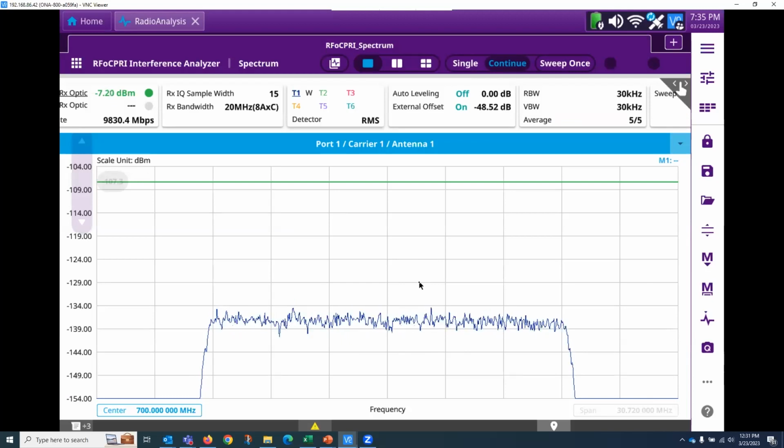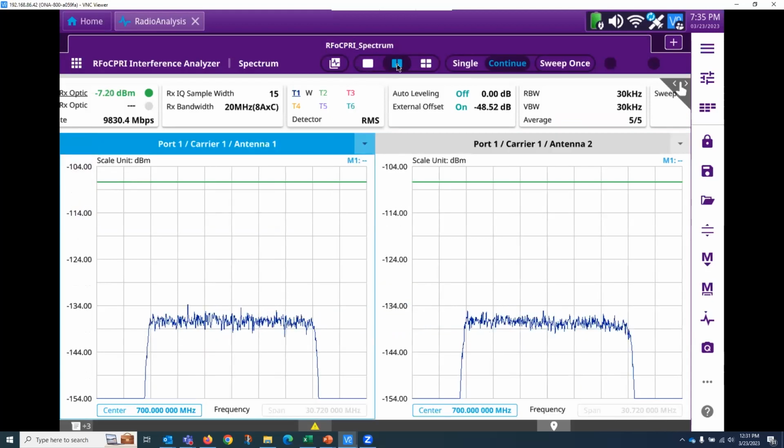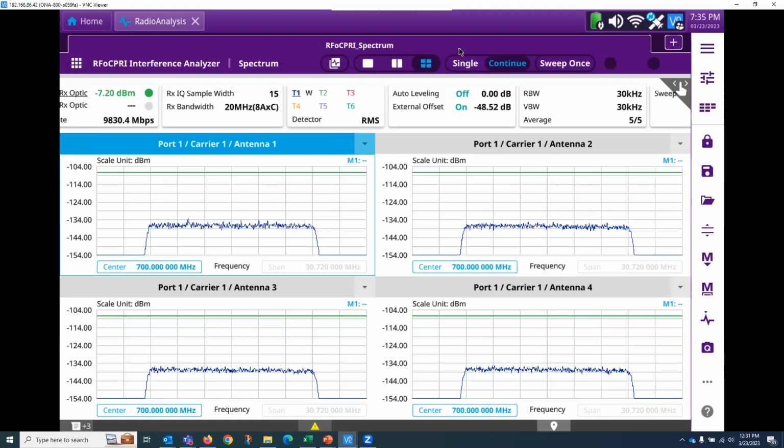Fairly quickly, the system is able to analyze a single antenna. If we're isolating one branch, or if I want to isolate two branches, I can come here and pick my branches, but more importantly, isolate all four branches. So this is our 4x4 MIMO system. You can see we have 4 branches. I do not have any PIM sources in right now, so it looks nice and clean.